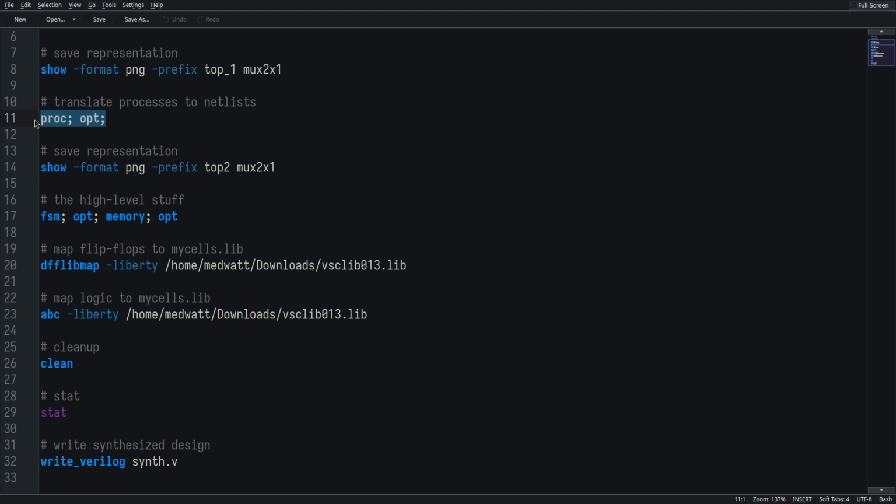Inside these processes you have things like if-then statements and case statements. Usually this command will try to implement what's inside the if statement into things like muxes and all of these sorts of things. Then we can see the difference between the stage before this translation has gone into it, and after this stage. If you have things like FSMs, there's a special way to optimize them.